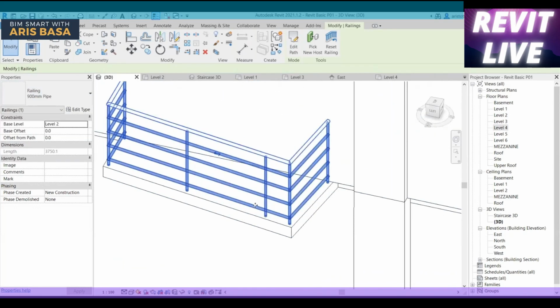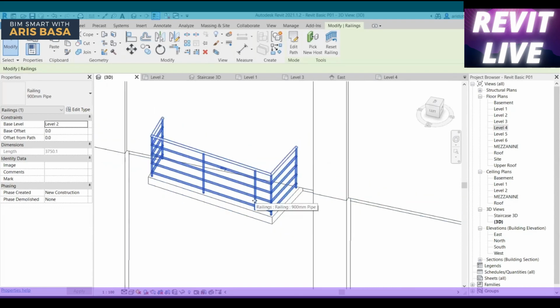Actually, this is not safe, even if it is 2 meters high. Why? For practical reason. Why is it not safe? Maybe because of the child. This is your problem, it is for the child, no? He can climb easily. It's like a ladder. But if it's vertical, it's difficult. But not too big, otherwise the head will go in. So that's why the others now mostly just use glass, tempered glass. At least it's solid. You don't distract the view, and it is safe.